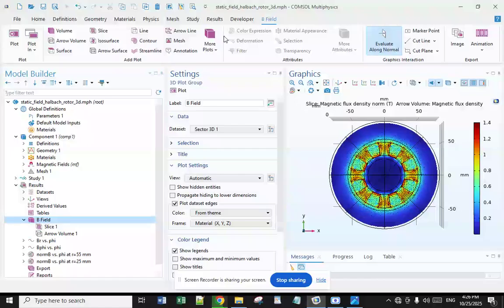The diagram shows the field from a strip of ferromagnetic material with alternating magnetization in the y direction, top and left, and in the x direction, top and right. Note that the field above the plane is in the same direction for both structures, but the field below the plane is in opposite directions. The effect of superimposing both of these structures is shown here. The crucial point is that the flux will cancel below the plane and reinforce itself above the plane.